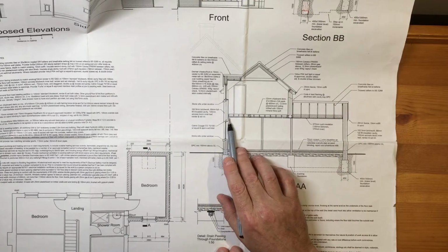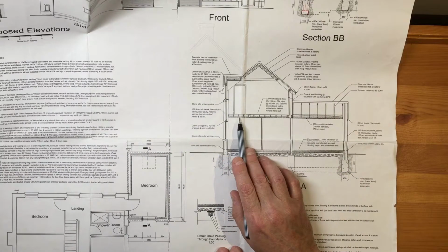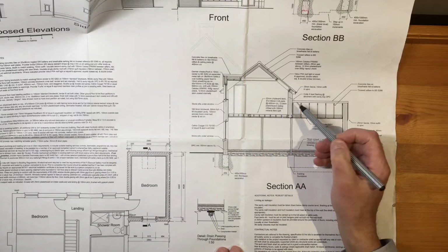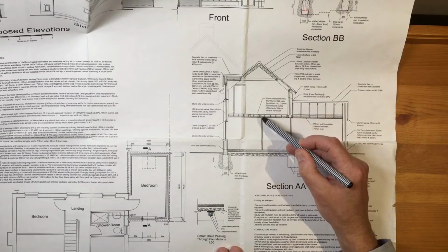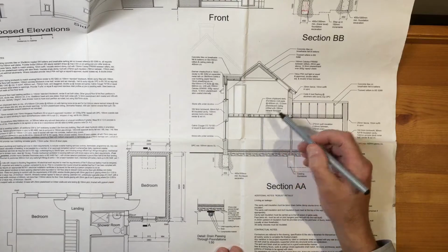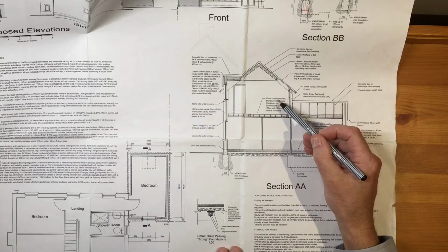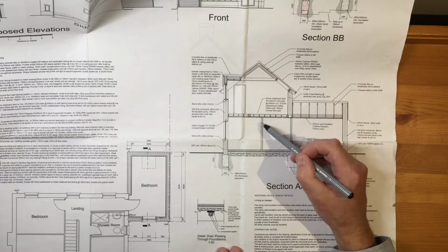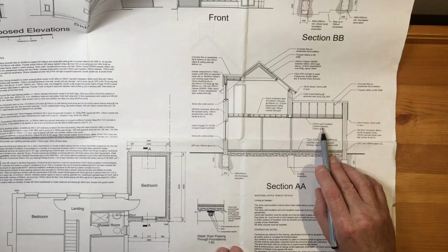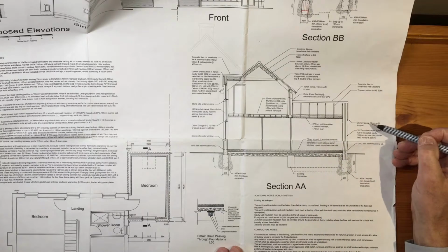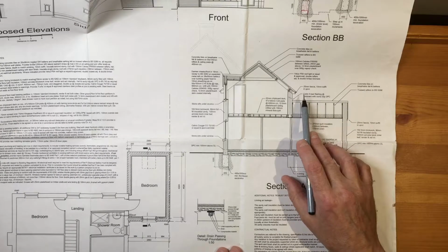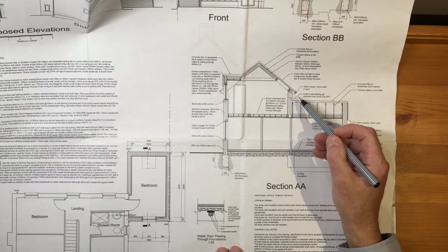building. And it even shows, look, the floor joists. Oh yeah, look. And this fluffy stuff, what do you think that is? Insulation. Insulation. And often it tells you in the detailed notes what comprises the piece being shown. So it says here about having a chipboard floor, and it will talk about the joists at some point, and the quilted insulation. And it talks about the fascia here and so forth, and the damp proof course, which has been incorporated here within the wall.